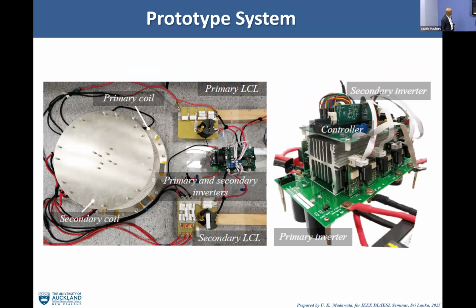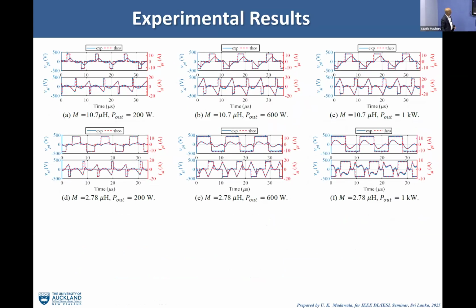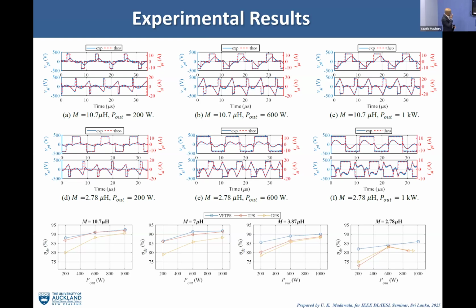And these are some of the systems that we built. There you can see with normal control. And you can see from here A, B, C, different coupling. That means the coupling has changed, but still we can balance from 200. This is for the 1 kilowatt system. Maximum efficiency in comparison to oil-based control. See, the blue curve is the oil-based maximum. We can regulate power. There's another one here, and you can see the coupling changes, different couplings, and you can see that my blue curve is still the maximum power.